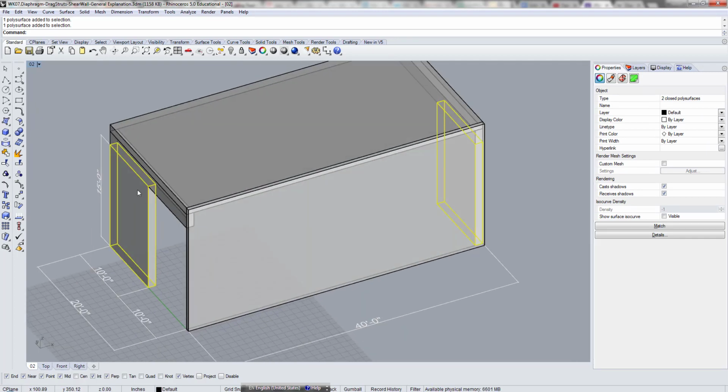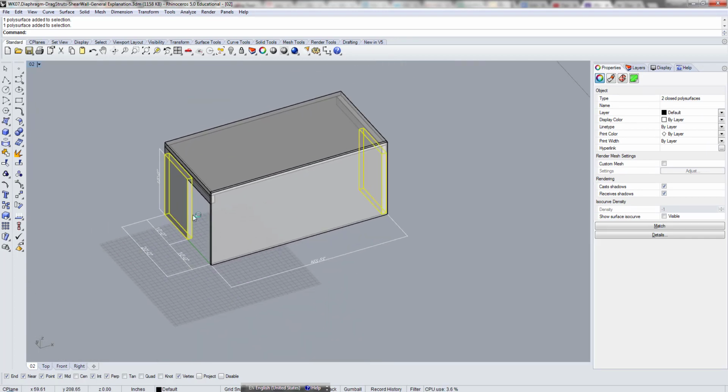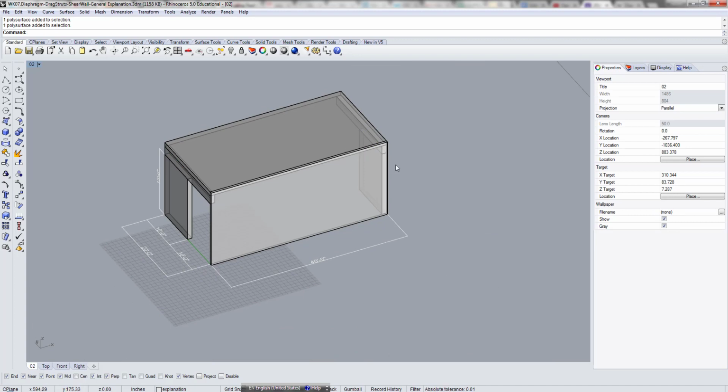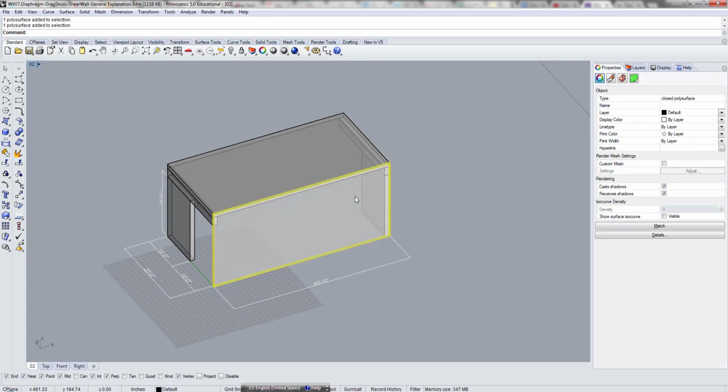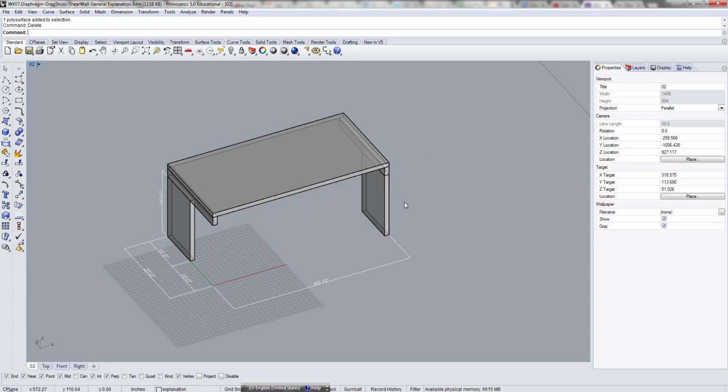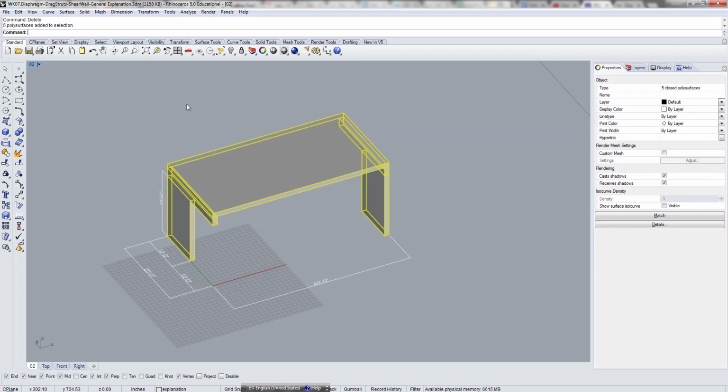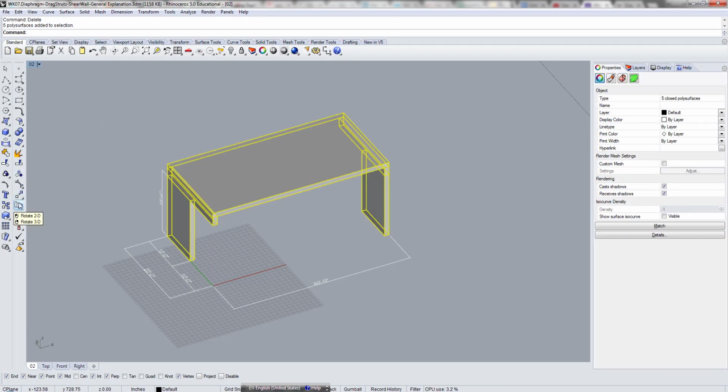And so all these spacings, and what you should note is that these shear walls are not extending beyond the entire length of the building. So that's only covering half of the building length. And again, if that's a curtain wall, right, that's not resisting any lateral force. So if you consider this as an actual building, then it's not good for resisting a lateral load this way. If there's any lateral load in this direction, this thing is just going to flip. And that's the end of the day.